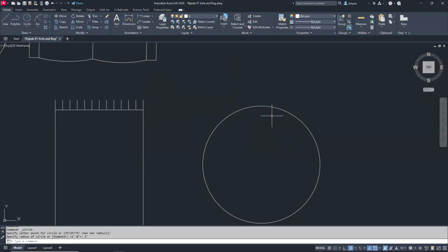And then I want to start with one line. So I come over here to draw a line. And I want it to go right here at that point. And this is what AutoCAD will refer to as a quadrant point. Now, you'll see that it wants to snap to the center. It also would like to snap to an endpoint, an intersection. I don't have that quadrant.